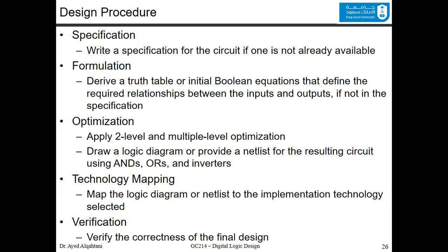After you do the formulation, you would do the optimization. In the optimization, we apply the 2-level and multiple-level optimization that we studied to finally generate or draw the logic diagram or provide the netlist for the resulting circuit using ANDs, ORs, and inverters.